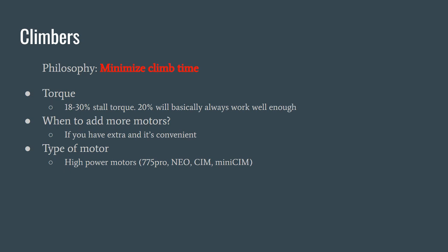And generally, you want powerful motors. That's the thing, because it's only used very shortly during a match, so you don't have to be as worried about damage. We probably should just try it. Like I said, the open motors don't like to be stalled, but when you're climbing, you're not stalling the motor. You're moving up the whole time, basically. So that's okay.